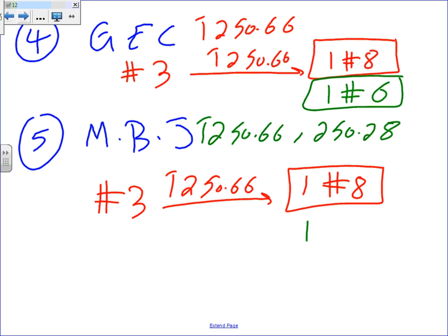So I would use number 6 for both of them. The minimum that you should use in a panel is number 6. Strictly speaking, the table can allow you to use number 8, but smaller than number 6, you have to provide physical protection for it, put it in a conduit. If it's EMT on both sides of the conduit, then you get into a whole lot of issues.